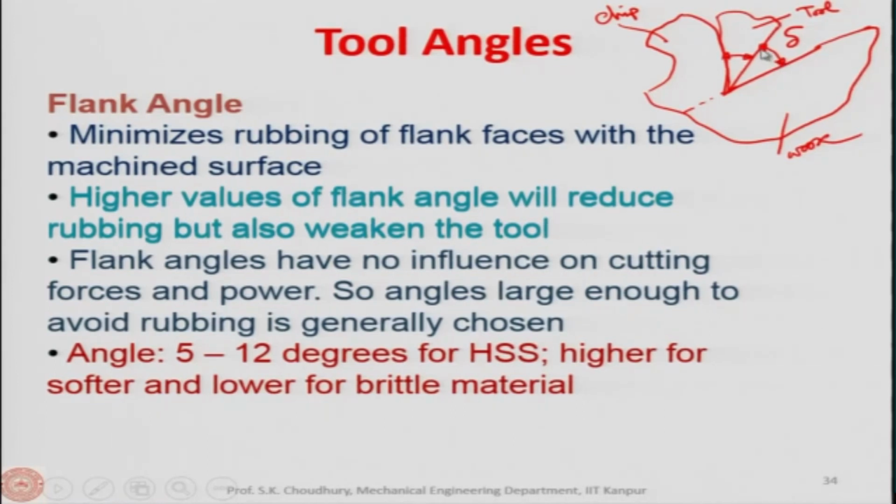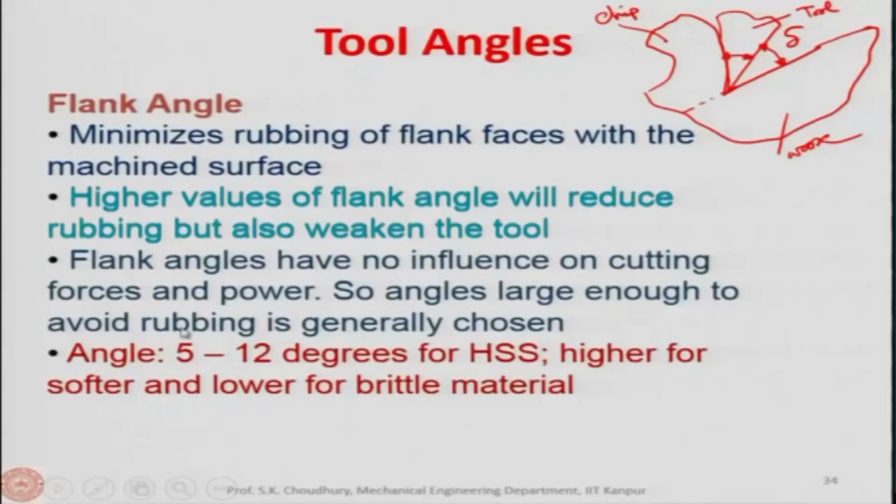Therefore, we cannot increase the flank angle infinitely, like in the case of the rake angle that we have discussed, because it will weaken the tool. Flank angles fortunately have no influence on the cutting forces and power like the rake angle. So angles large enough to avoid rubbing are generally chosen, because we are safe.